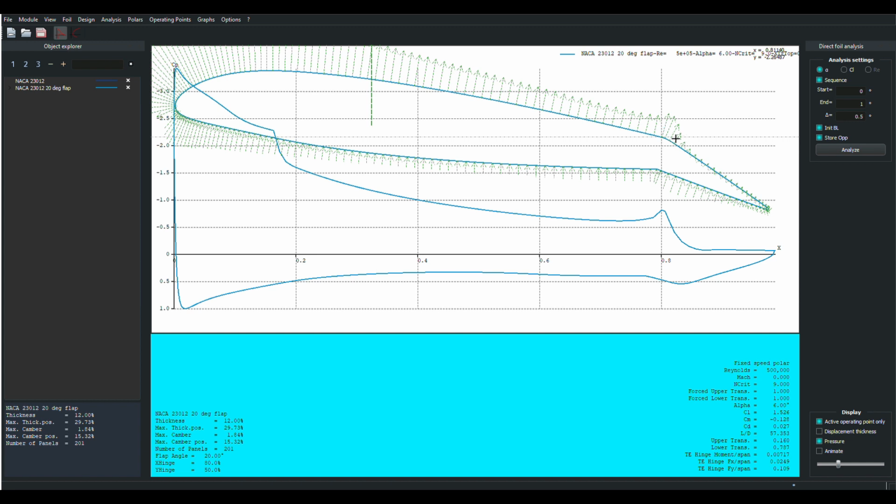You got an adverse pressure gradient, and you got to turn a corner, and the flow has no inertia left in it. So this is why when I moved my hinge line way up here near the spar on my wingtips, it actually worked out okay. If you're close to the maximum thickness point, you have much more inertia in the flow, and it can get through the adverse pressure gradient, get around the corner and stay attached to the wing, and make it through the rest of the adverse pressure gradient.